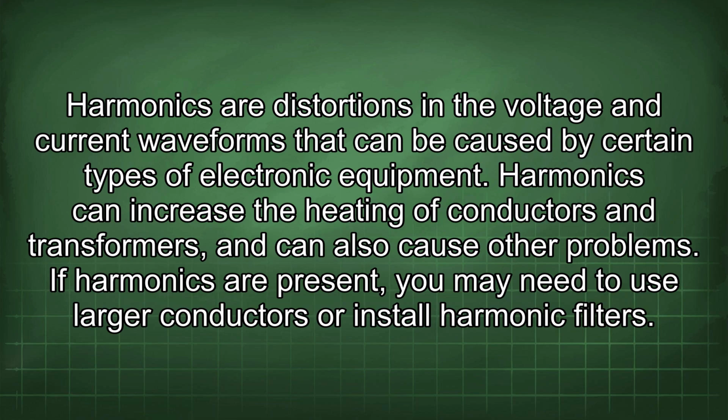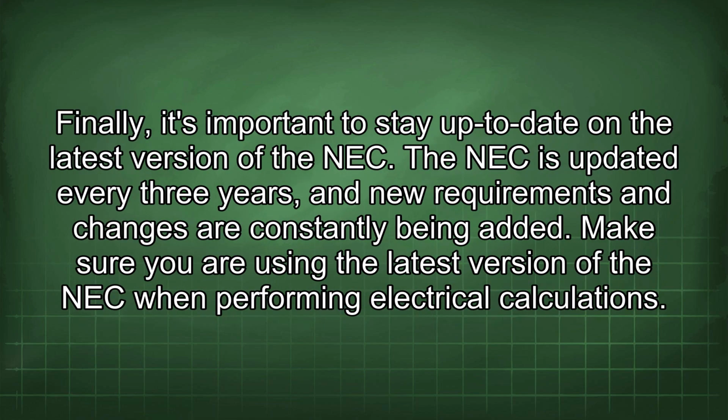Harmonics are distortions in the voltage and current waveforms that can be caused by certain types of electronic equipment. Harmonics can increase the heating of conductors and transformers and can also cause other problems. If harmonics are present, you may need to use larger conductors or install harmonic filters. Finally, it's important to stay up to date on the latest version of the NEC. The NEC is updated every 3 years, and new requirements and changes are constantly being added. Make sure you are using the latest version of the NEC when performing electrical calculations.